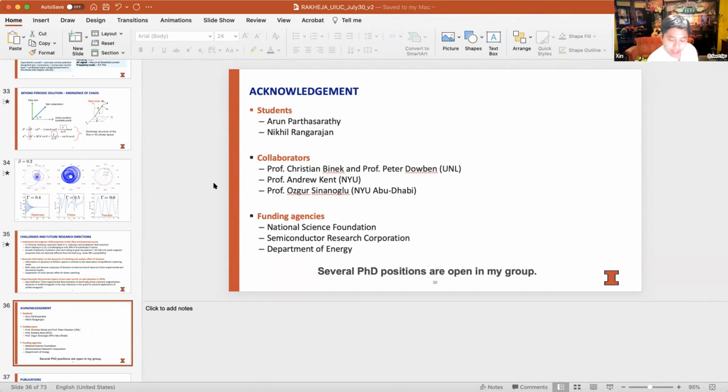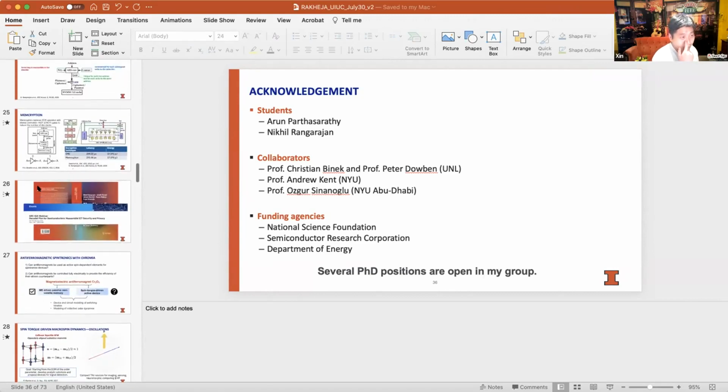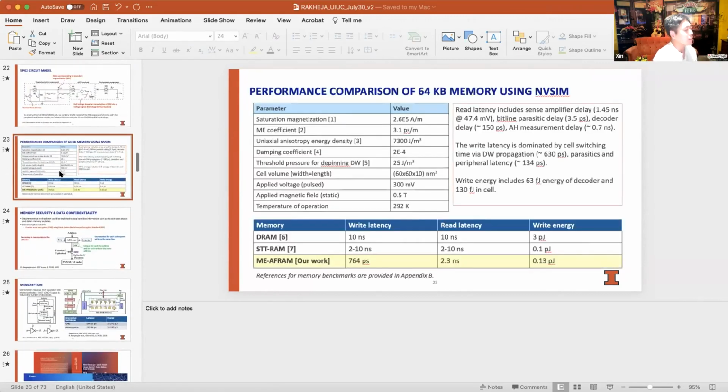Thank you very much for this very interesting talk. I actually have 2 quick questions. On slide 23, you simulated the write latency. That's still based on the domain wall motion model, right? It's just the device is small enough, so the switching takes shorter time. How small is that? And are you able to actually move to a single domain region where it just becomes completely coherent switching?